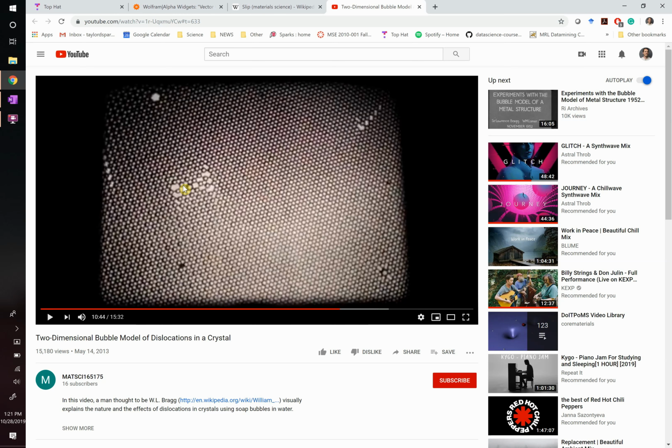So if that dislocation stays where the copper atom is, instead of keeping on moving through, did you make your material harder or softer? Yeah, you made it harder. If the dislocation can't move through your material, then you don't get deformation. So you made it a harder material.